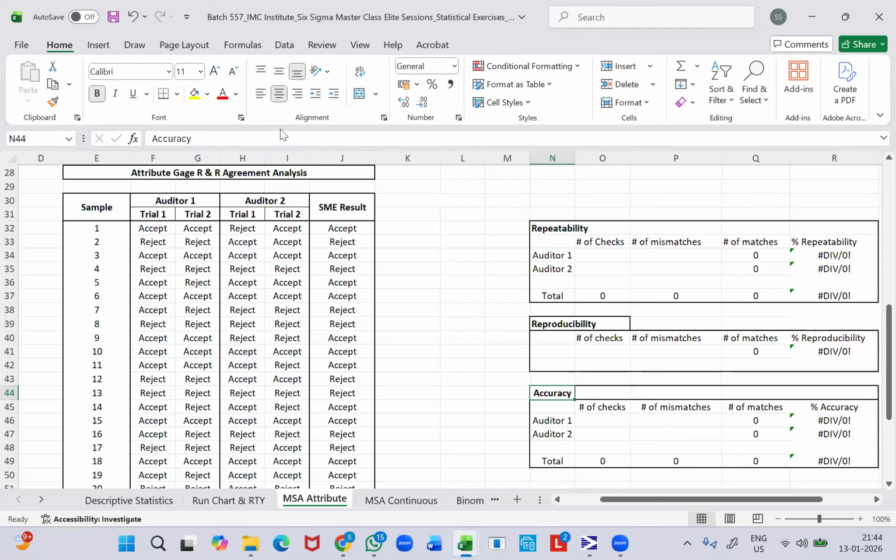So all these three metrics, which would actually represent the measurement system variation, the variation percentage should be less than 10%. If the variation percentage is going to exceed 10%, then we need to infer that the measurement system is not working fine, and we need to discard the data provided by that measurement system, correct the measurement system and collate the data once again. So for all these three measurement system variation metrics, we need to have the variation percentage less than 10%.